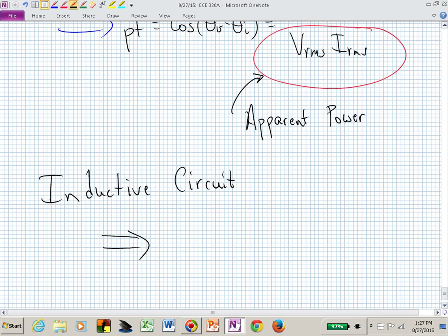Now maybe I have a mix, but it's still going to be off a little bit, isn't it? It may be between 0 and 90. But what do we know about the current and the voltage? Which one's ahead or behind? If I said the current blank voltage, lags. So now we know that in an inductive circuit, the current lags the voltage.